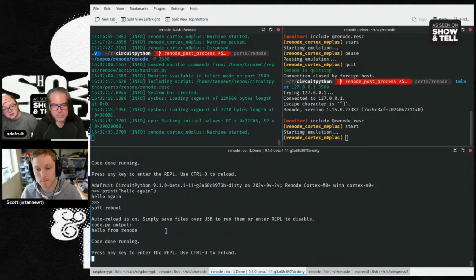So is the idea here that you want to eventually make it so any emulatable Zephyr chip could have CircuitPython ready to go for it? Like you wouldn't have to do the beginnings of the port? My goal was to have the system be the same, but be able to swap different CPUs in potentially. This is a Cortex M0+ board, but we could also have a Cortex M4 board as well. Yeah. And then it would run the emulation on the M4 with different compilation instead. Okay.